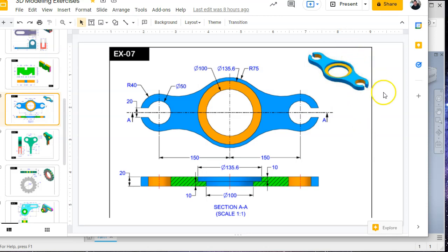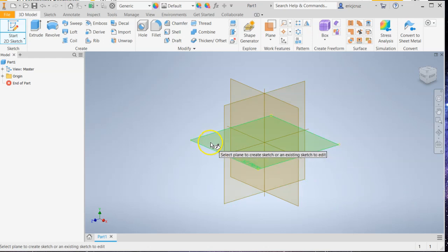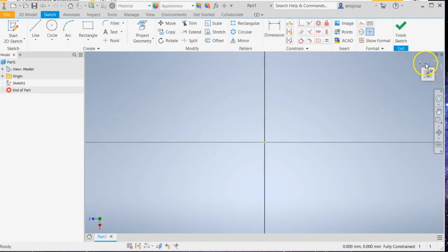and before you actually start a 2D sketch, we're going to be drawing on a different plane for this one as well, because the top view is this plane right here, the XZ plane. So click on the XZ plane, and your view cube is going to look like this. It's going to say top, and it might be tilted. So you need to click on this arrow here to spin that around so that we get the correct view.